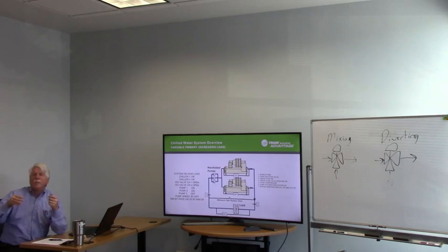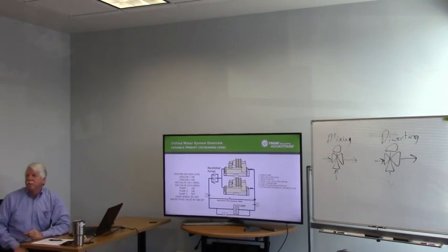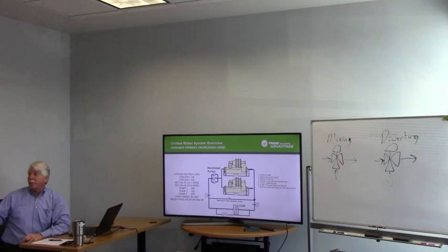But for all the chillers that are enabled, you have a DDC loop running for minimum flow. And whoever wants that bypass valve open the most always wins. So if one of them wants it 10% open and one wants it 25% open, you open it 25% because you have to maintain the minimum flow in the critical chiller.